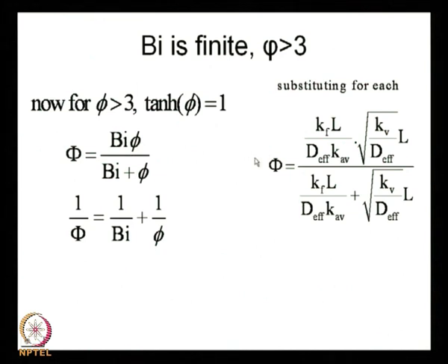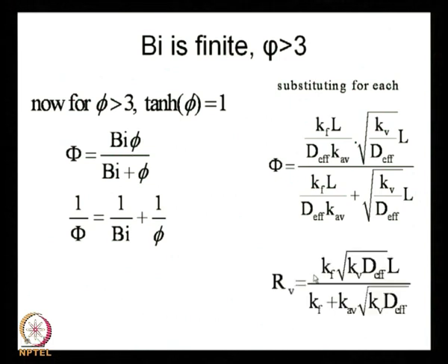So, this is one limit that we are looking at, and to go a little quick today, because I am going to finish this little bit. Fine. So, now your Rv, that is your observed reaction rate, you can measure in terms of this, and this is the expression that you get. If you want, you can write it down. So, this is proportional to Kf, the mass transfer coefficient, Kv, the partition coefficient, D effective diffusion, and length L.